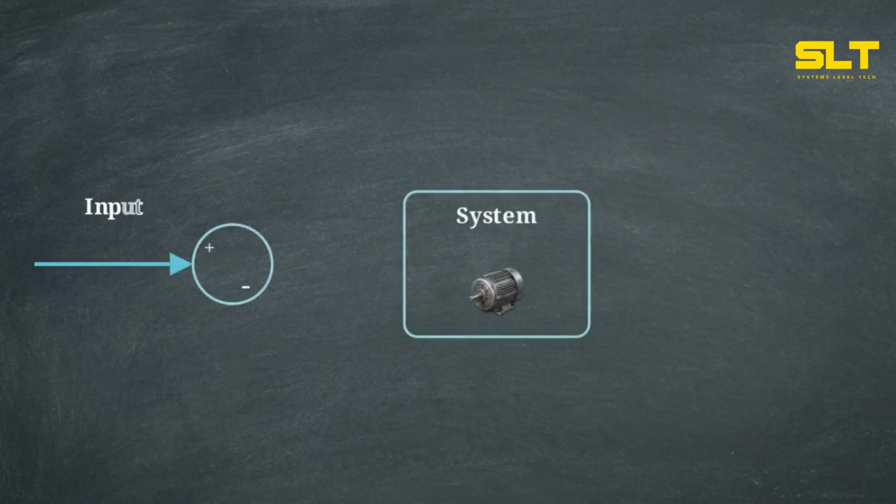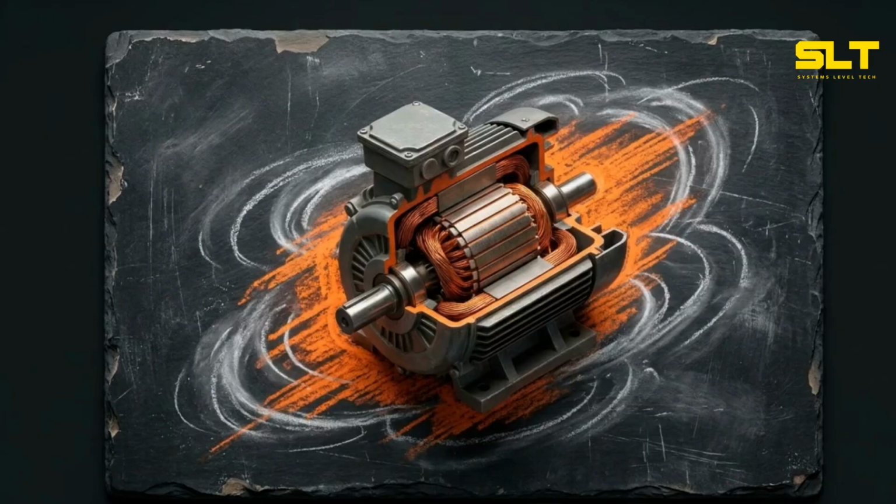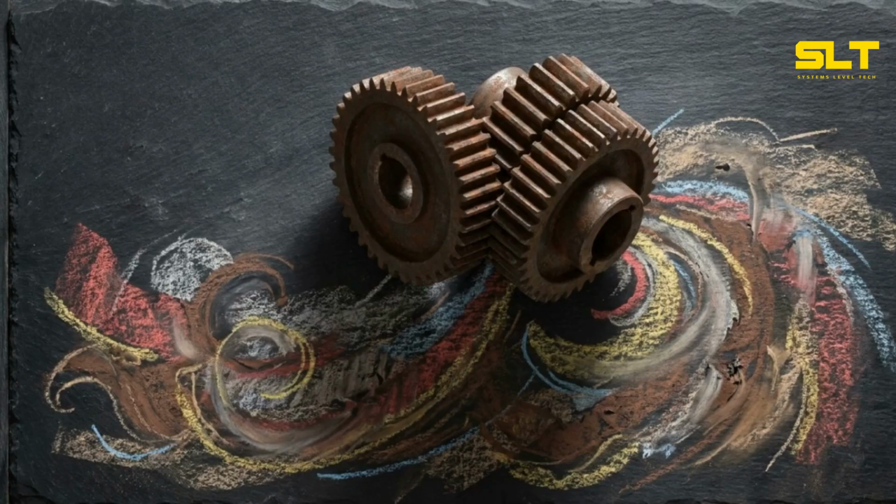Because of its closed-loop architecture, the system instantly detects the change in its own output and calculates this newly introduced error. The feedback loop triggers the motors to increase torque and push back against the wind, entirely independent of human command. We do not adjust the input dial to fight the wind. The machine is designed to reject the disturbance internally.